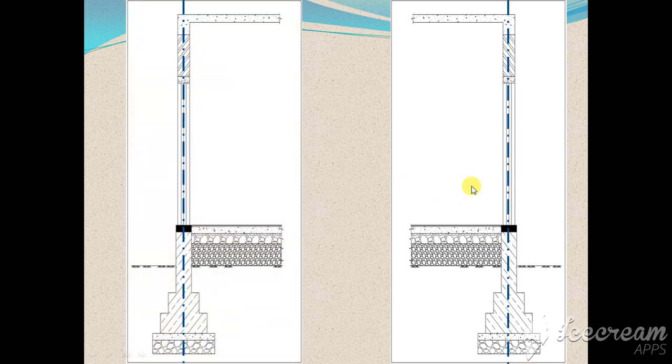In the last video, we have seen the centerline method and the long wall short wall method, and how to use these methods for load bearing structures. The most important part that we have seen is that both of these methods can be used only for those items of work which will be divided equally by the center line, which is shown over here.